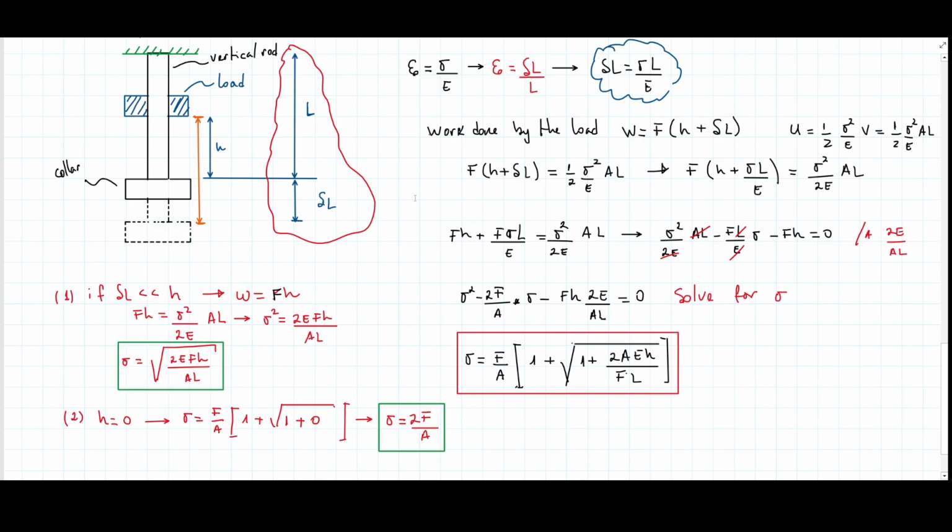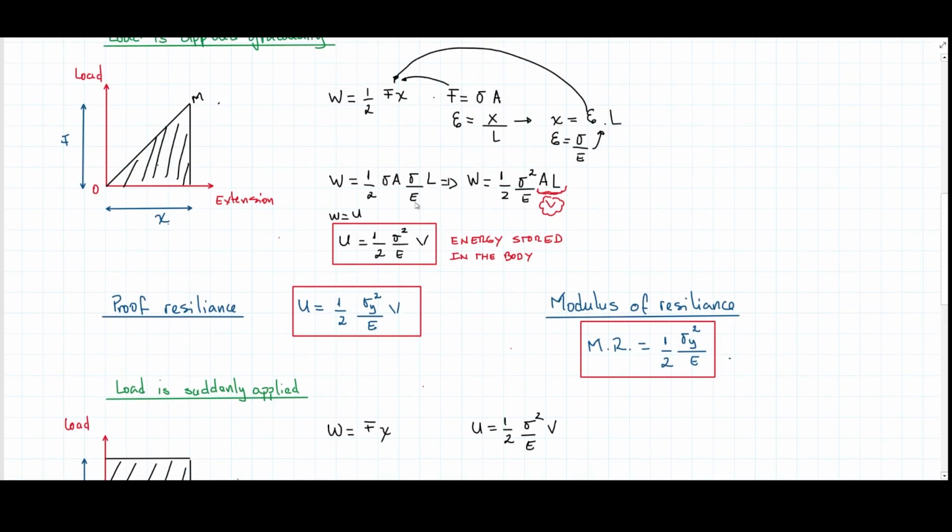Okay, so awesome. We saw three cases, but this is just for a point load applied on a body. For strain energy methods, or energy methods in general, you can calculate the strain energy due to point loads, as we have done. You can also do it for shear stress on the body, moment on the body, torque on the body, distributed force on the body. There are several cases that we could look at, but in this case, we're going to restrict the whole introduction to point loads. We're going to take a look at shear stresses, and we're going to take a look at bending moments. Bending moments are the ones that are going to allow us to come up with a practical application, one of the many, of strain energy for deflection calculation.